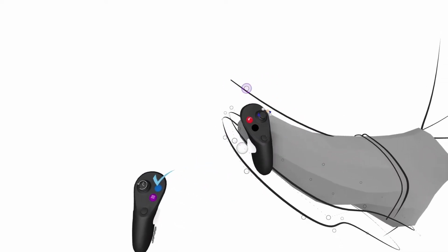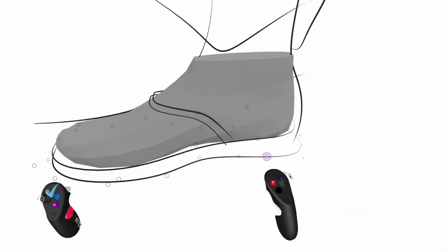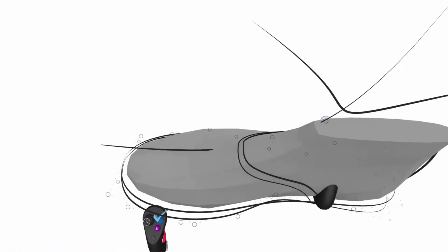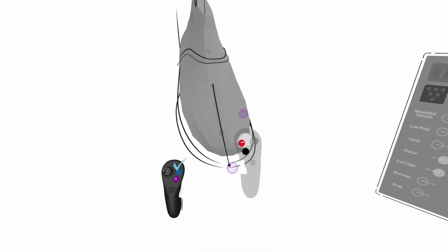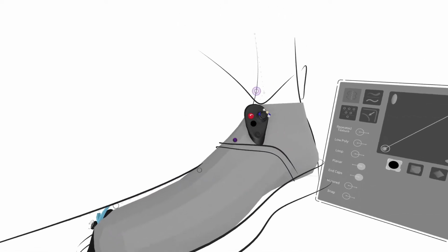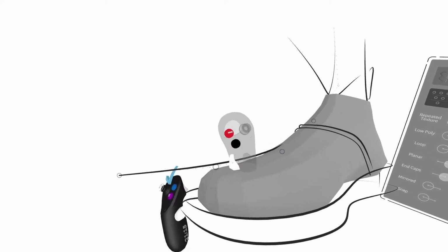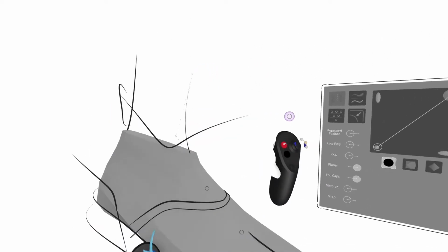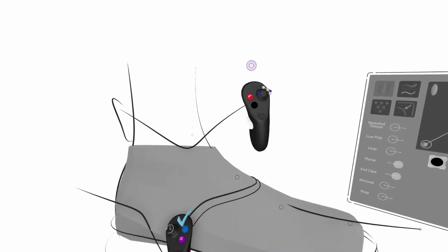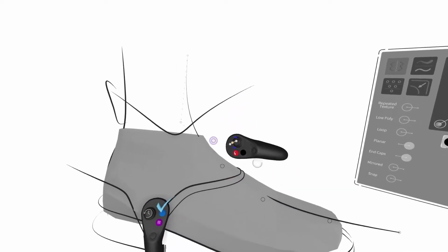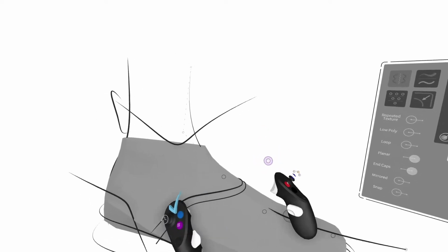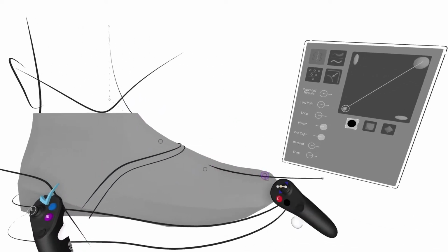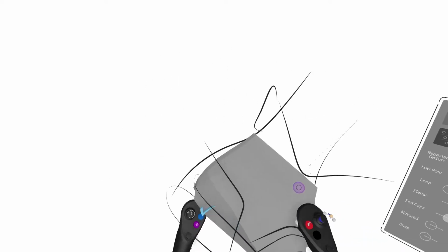So again, it may not be the perfect workflow for taking it straight to manufacturing, but it's a good workflow just to get your idea out in 3D. And you could cheat things as well. So I imagine if this was a flexible upper in terms of the material, the shoe would take the form of the actual foot once it's in there. So I kind of feel comfortable leaving that center line in there where it intersects with the shoe last.